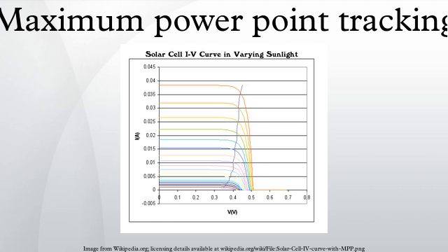Solar inverters convert the DC power to AC power and may incorporate MPPT. Such inverters sample the output power from the solar cell and apply the proper resistance so as to obtain maximum power. MPP, maximum power point, is the product of the MPP voltage, VMPP, and MPP current, IMPP. Some solar panels have a higher maximum power than others.